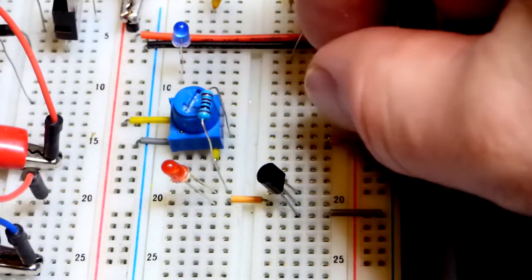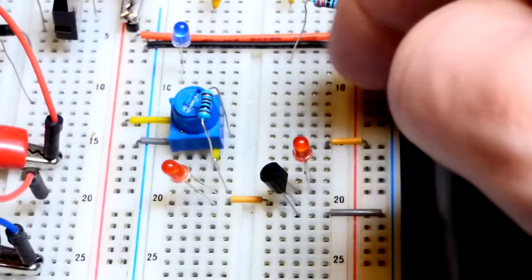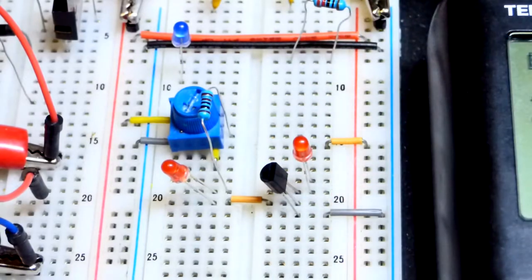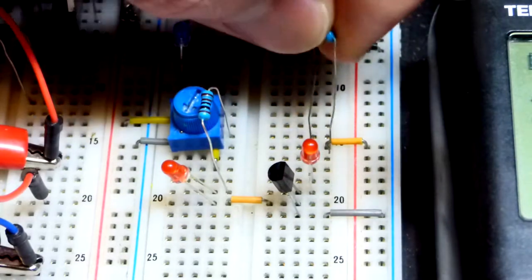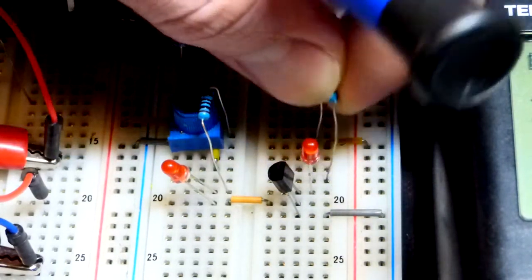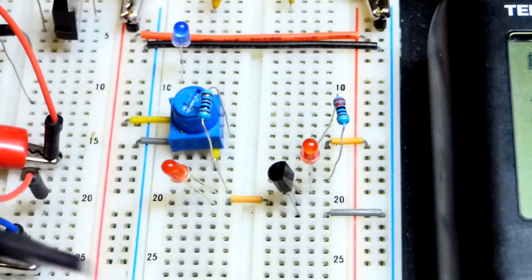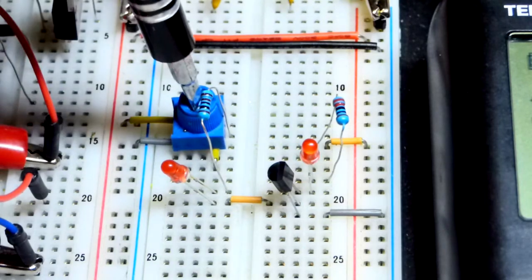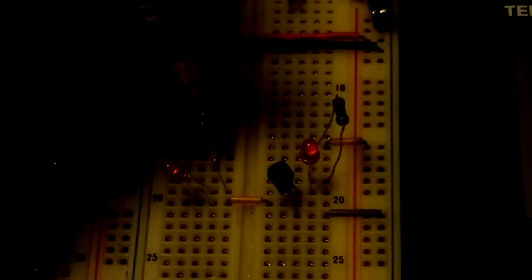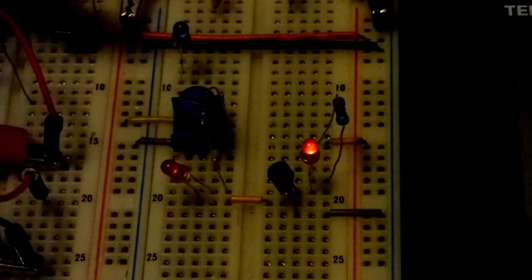So now we're going to add an LED to the collector. Of course, the long lead has to go towards the more positive side, and the short lead towards the more negative, for it to light up. It's a diode, it conducts in one way. And now we'll grab a 220 ohm resistor. There's no base current right now, and so there is no collector to emitter current. So I'm going to turn the lamp off, I should say. And let's slowly turn this up. You can see that LED is getting brighter.